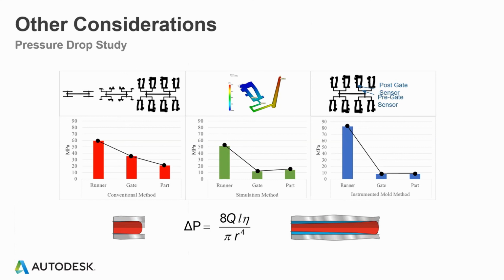So in this case, simulation does a good job of the trend, not necessarily the magnitude, but we've already mentioned a number of reasons why things can be different on the magnitude side. So there's still probably work to be done there, but it certainly does a better job of capturing the trend correctly. And what this amounts to, and why you may want to go back and look at the previous presentation from 2018, or even read an article that John Beaumont wrote in the SPE magazine, is that we're not accurately capturing the frozen layer development by stepping back the flow path.